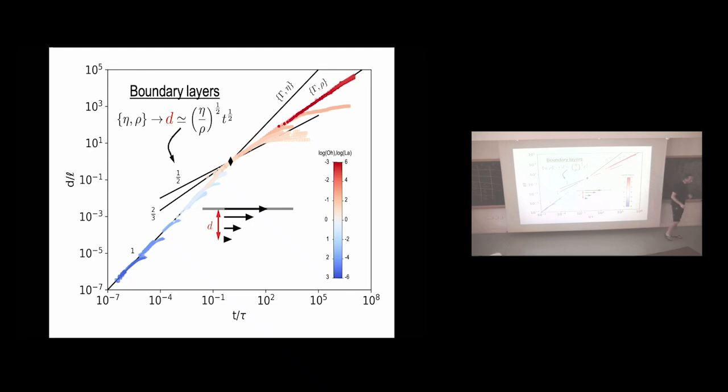In the case of the water droplets, you don't have like a plate that is moving like this. It's more complicated than this. But this scaling you find in situations also where the kinematics are a little bit different. So for instance, if you have a flow where the plate is not moving, but it's a uniform flow far away from that plate, and it's hitting the plate, the size of the region where the flow is being slowed down will also follow this scaling.